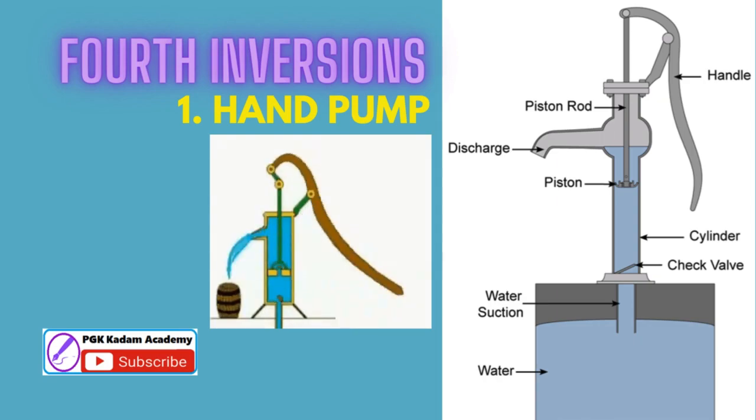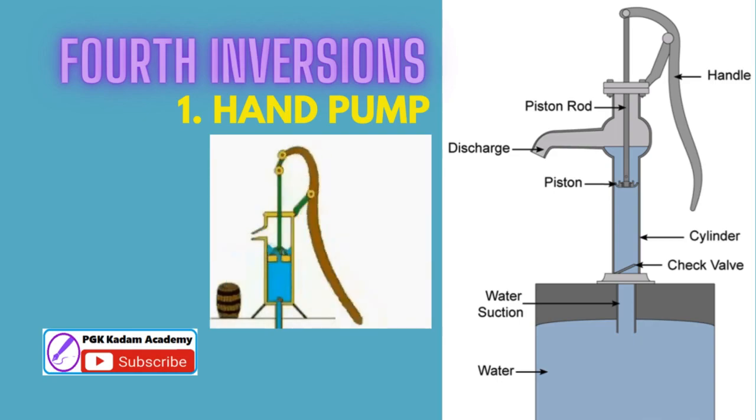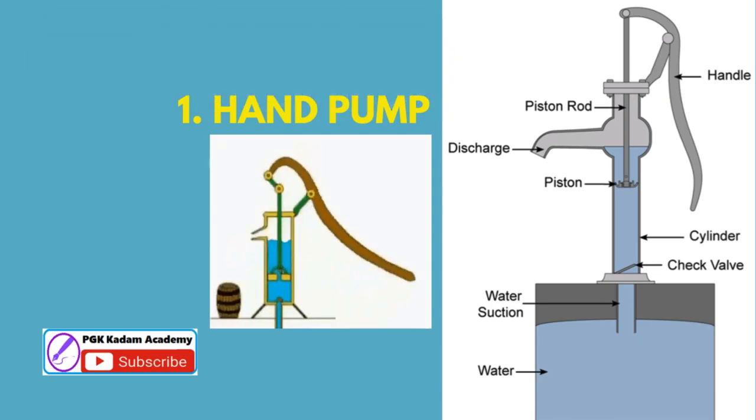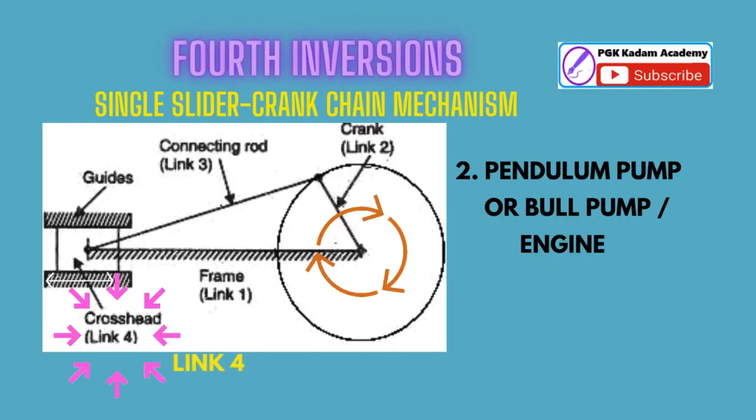The result of this movement is that water from the underside of the piston non-return valve is moved to the top side of the piston non-return valve. When the piston next moves upwards, it moves the water that is now present on its top side upwards also. Repeating this push and pull movement on the hand pump lever results in more liquid being drawn into the cylinder and the water level within the cylinder rising. As the water level rises, it reaches the height of the discharge pipe and begins to flow out of the pump.